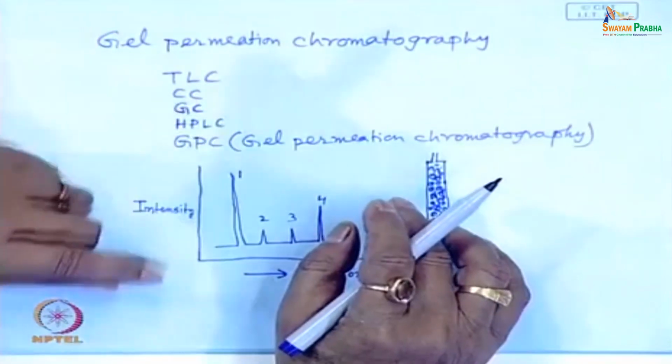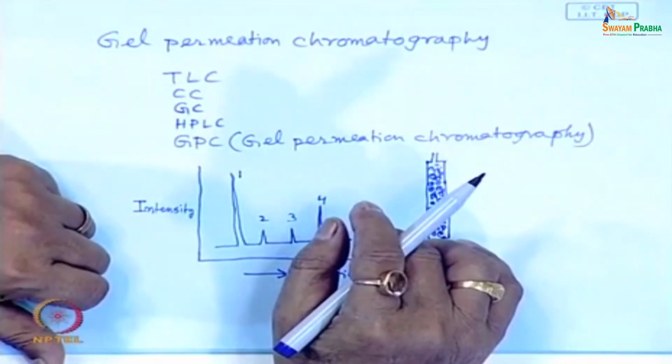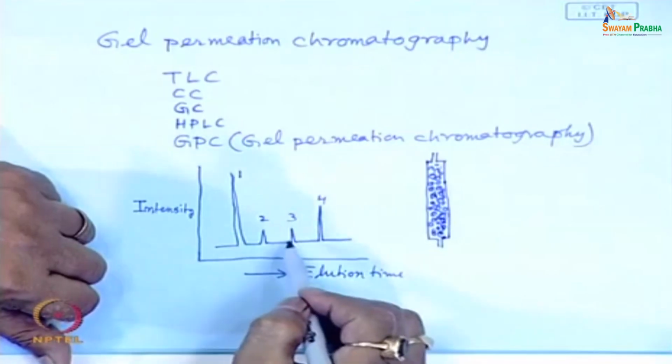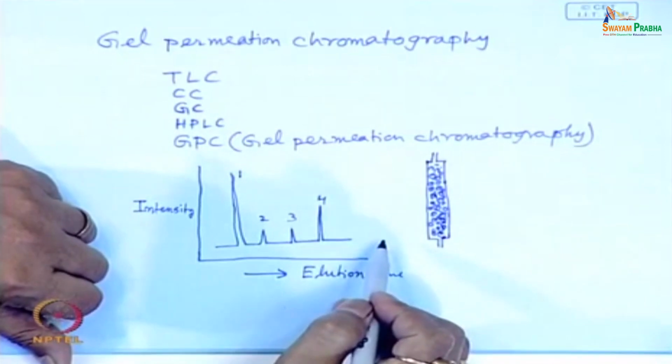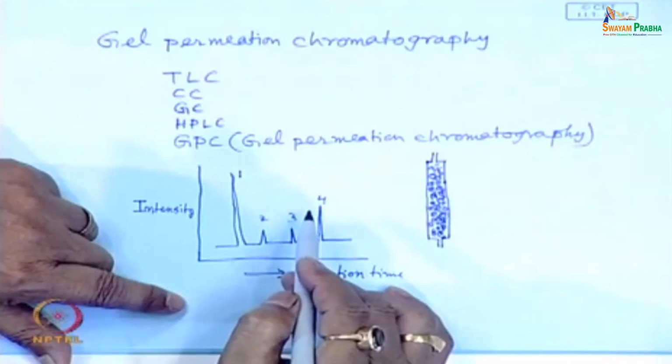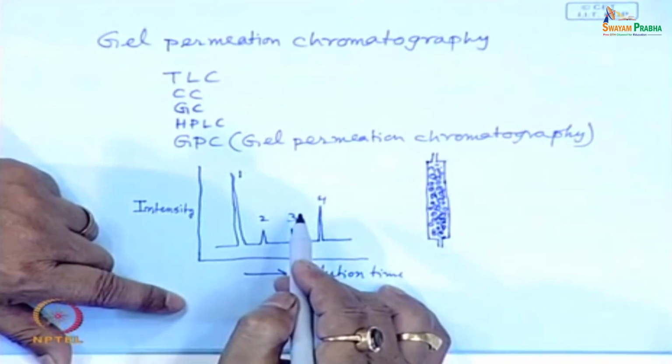that means a fractionated one, that passes through a detector that detects that it contains many different fractions, fraction 1, fraction 2, fraction 3, fraction 4, 5 like this. Now, if you have a calibration standard, a polymer of known standard molecular weight, first you have to run the GPC with the standard polymer of known molecular weight and plot a calibration curve.